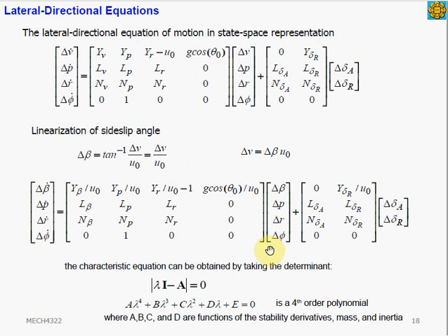In the textbook example of approximation, it states that although the side slip angle is small, we still do not want to drop this term, so we keep the side slip angle beta. And the aerodynamic contributions due to side slip and the yaw rate are on the same order of magnitude, so we keep these two parameters to approximate the spiral mode.